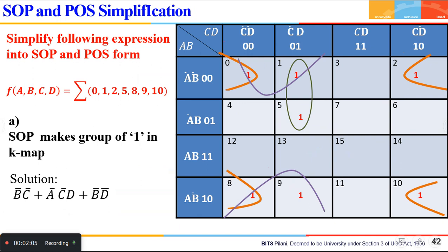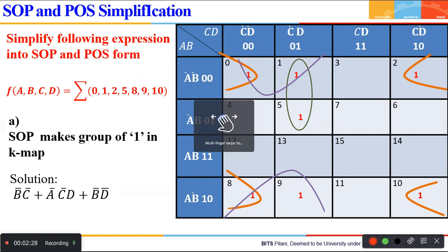Now you all know that there is one more form of representing Boolean equation. What is that? Product of sum. For that, I have told you in the beginning of Karnaugh map lecture that you consider zeros. Can you see here? For sum of products, when you put all ones, min terms, remaining places it is supposed to be 0.